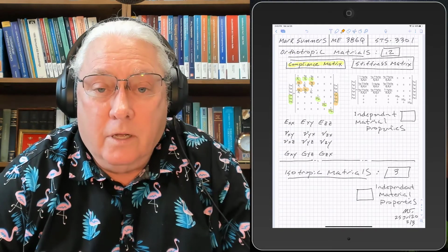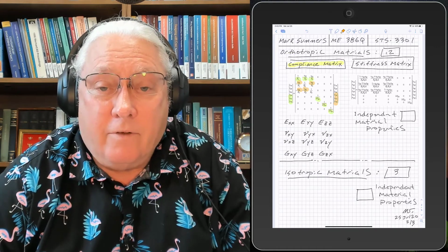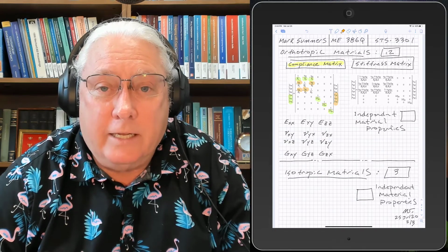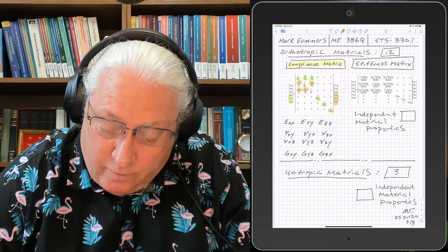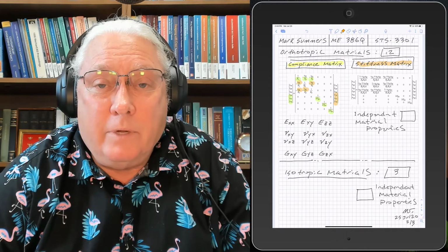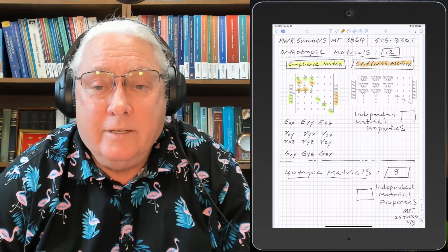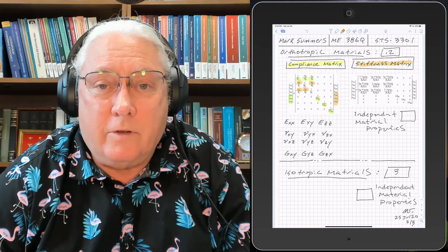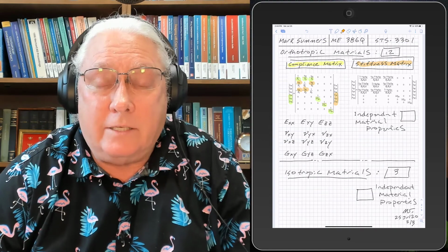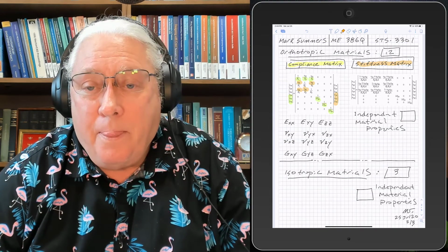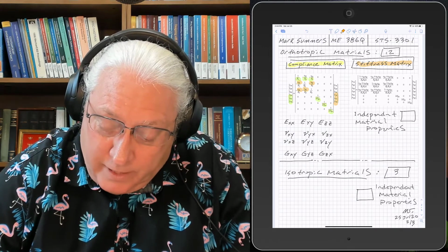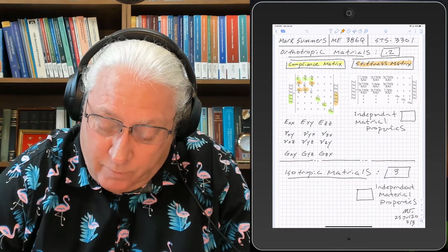And then if you do some matrix algebra and come up with an inverse matrix of the compliance matrix, so you multiply 2 matrices together, you get the identity matrix, you can get this other version of it, which is called the stiffness matrix, and this is what I'm used to seeing when we're dealing with finite element analysis calculations. Generally, you talk about the stiffness matrix, and that's the matrix that the finite element analysis program creates to calculate the displacements, and then the strains, and then eventually the stresses. And so you get the same parameters involved with it.